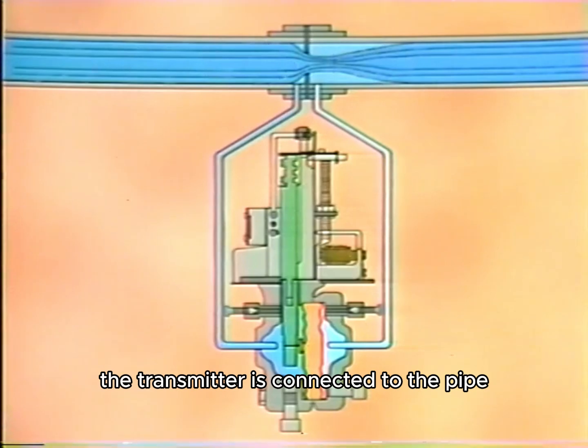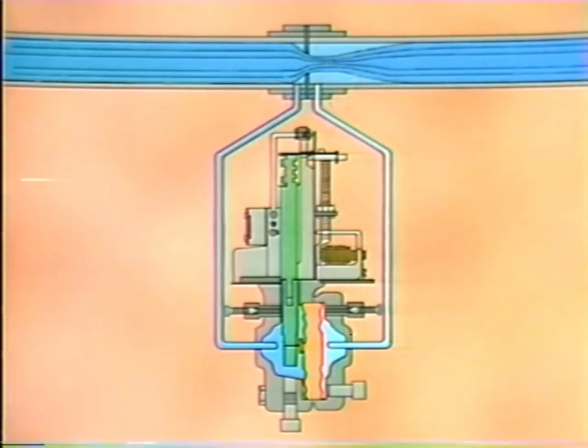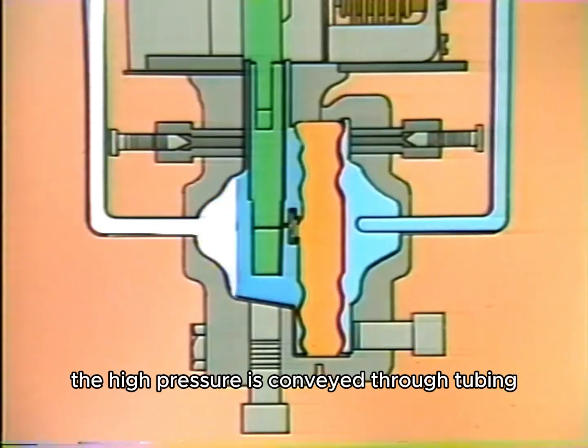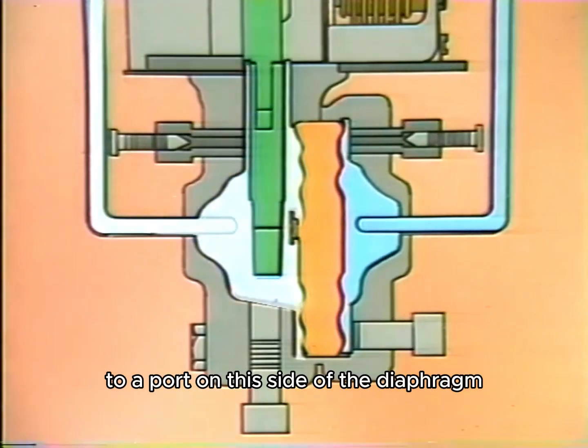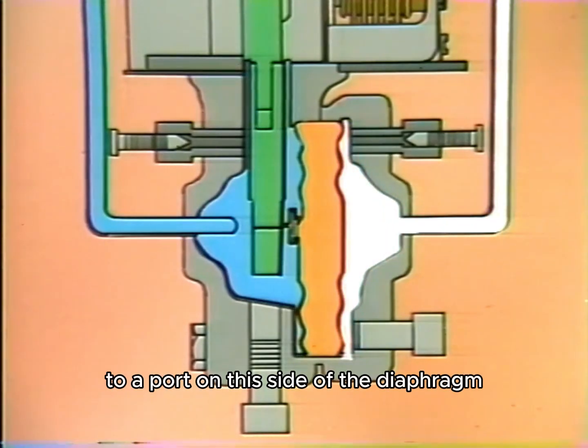The transmitter is connected to the pipe on both the high and low pressure sides of the restriction. The high pressure is conveyed through tubing to a port on this side of the diaphragm. The low pressure is conveyed through tubing to a port on this side of the diaphragm.